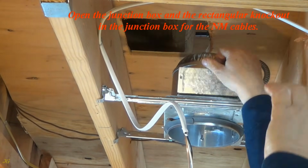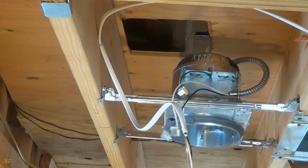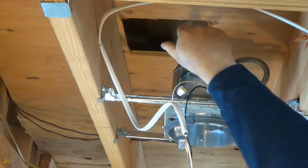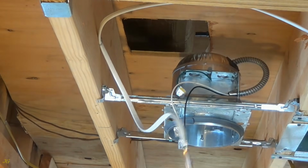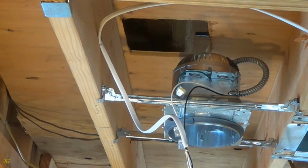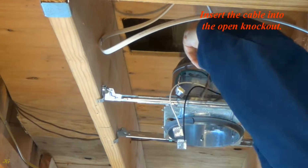Open the junction box and junction box rectangular knockout for NM cables. Insert the cable into the open knockout.